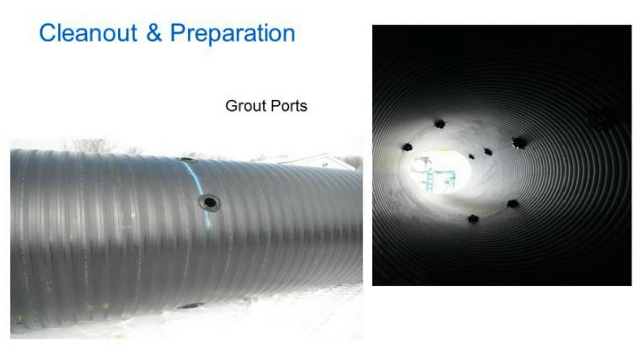These are a couple of ways to get grout in. You can also get grout in from a chimney, from pouring a hole in the top of, let's say, the embankment or in the median, if that works, and then you can actually just drop in grout from the top also.